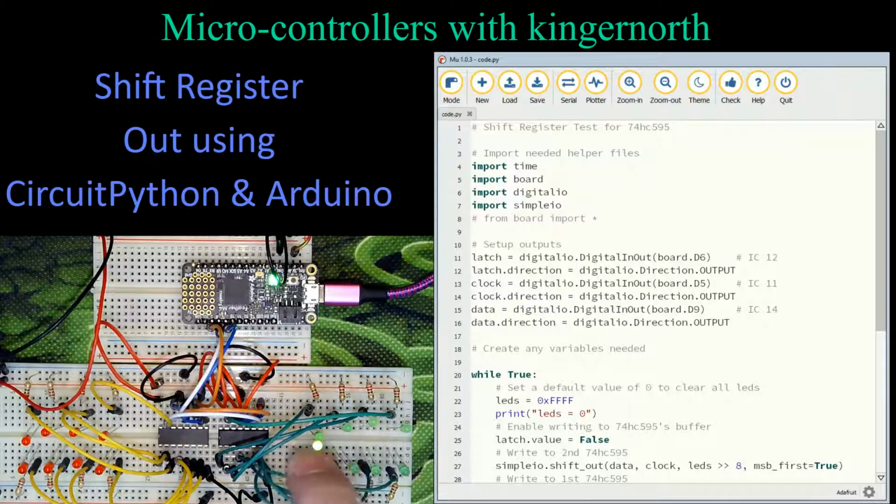So what I've got going on here, as I'm moving it, my first chip is this one on the left. That's the first one. The blue wire from the board connects to this data in. This is my serial input. And then my serial out is the other blue wire that jumps out of here and jumps over to this board. It just jumps in behind the little white wires there, mixed with the white wire and the orange wire, but they're there.